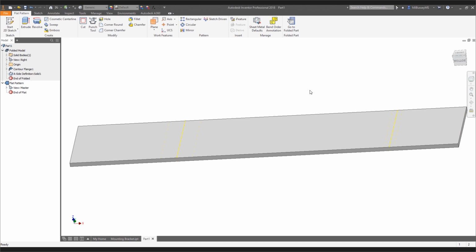I would put some iLogic into my sheet metal template that said, given these rules, if I'm between an angle of 0 and 25, this is the radius I should use. If I'm in the second range, then this radius. I mean, I'm thinking off the top of my head. But if you want to contact us and you have some examples you can send us, we can take a look at it and probably give you a better idea of an approach to try. But off the top of my head, that's the way I would start to tackle it.